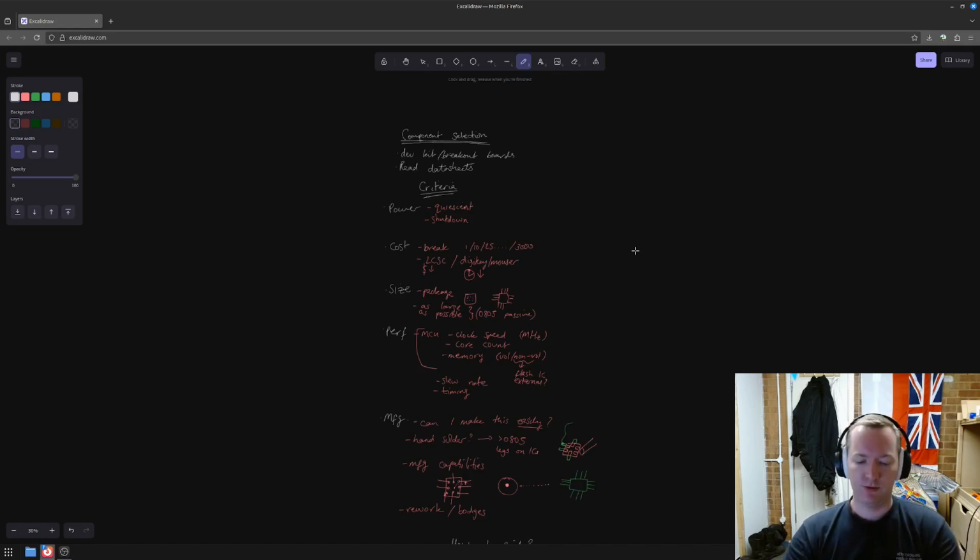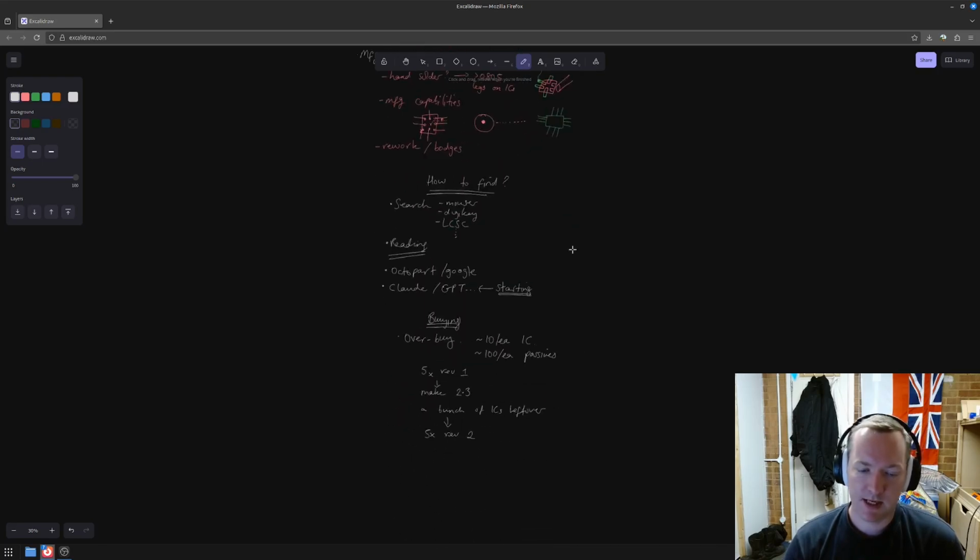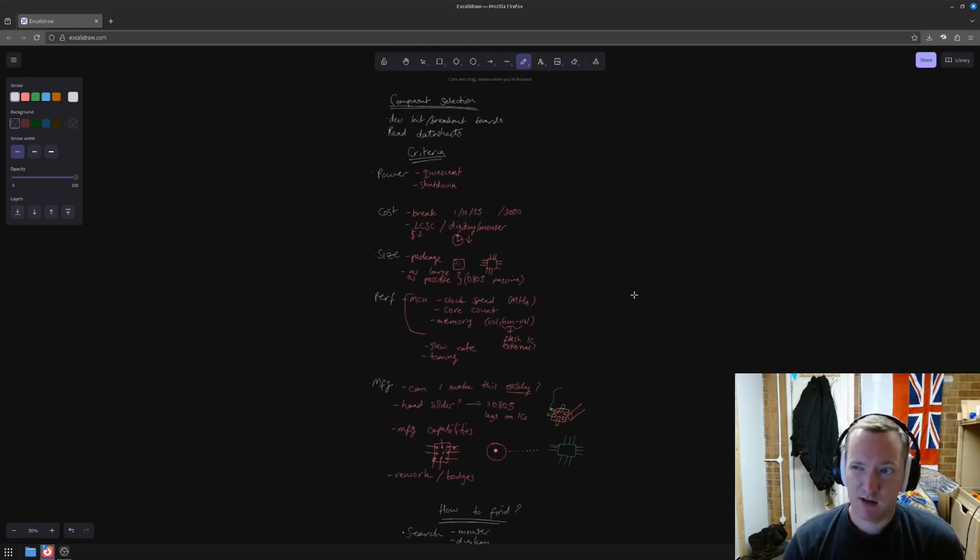Say you start with the power supply in your schematic. Okay, well, now I have to figure out the power supply. I know how much voltage in, voltage out I want. I know how many amps I need to supply. Okay, now I can make the power supply. That could be completely separate from your microcontroller choice. So you can just do little pieces of the schematic as you go, until it all comes together. There will be some things that you need to make a decision on as a whole, but usually the modular approach is the way to go, and having this in mind from the beginning can really help you with that.